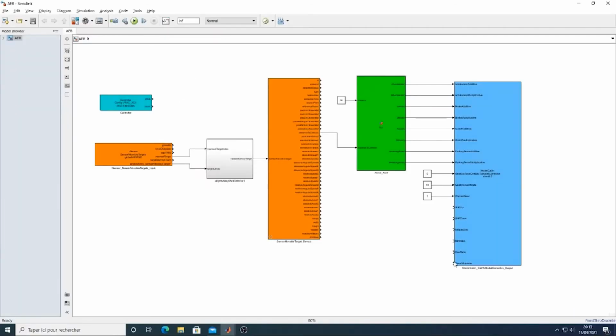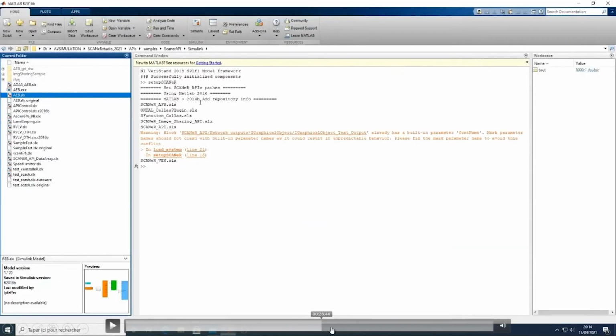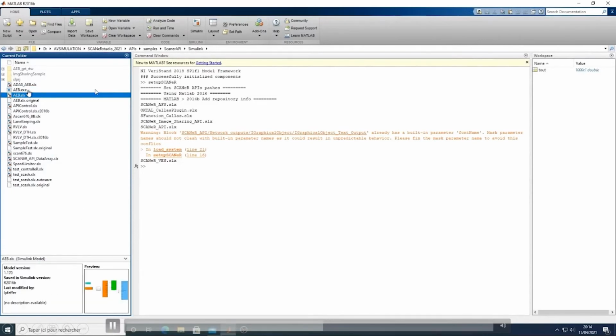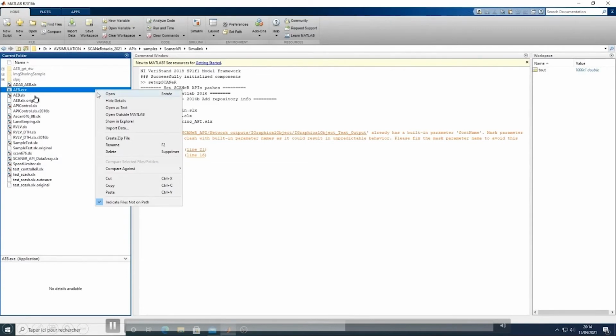So the process for that is pretty straightforward. Inside of Simulink, just select the compile button, which is on the top of the screen here. Just press it. I'm accelerating a bit. At the end, we get a .exe, which matches the model we have made in Simulink.